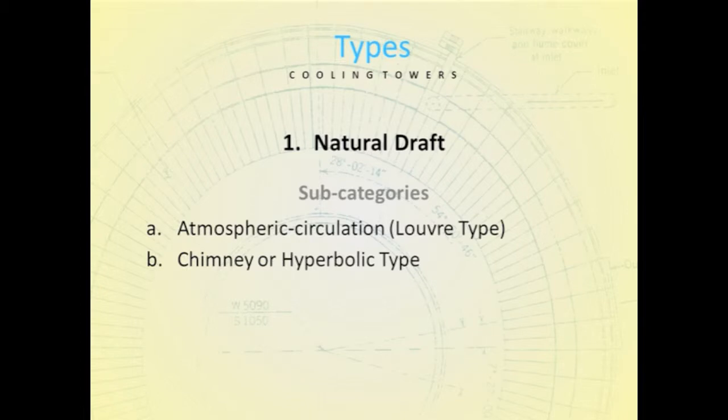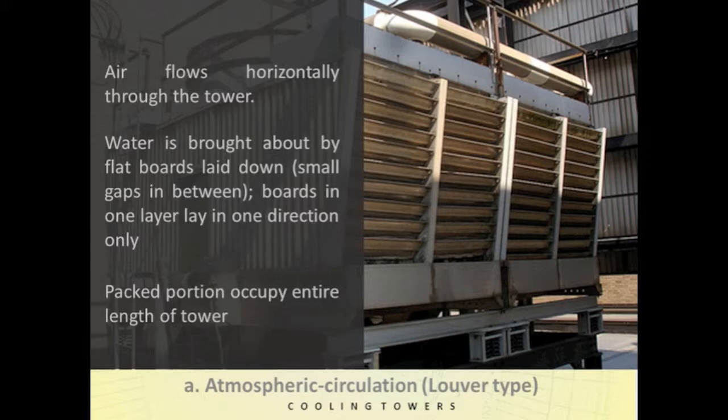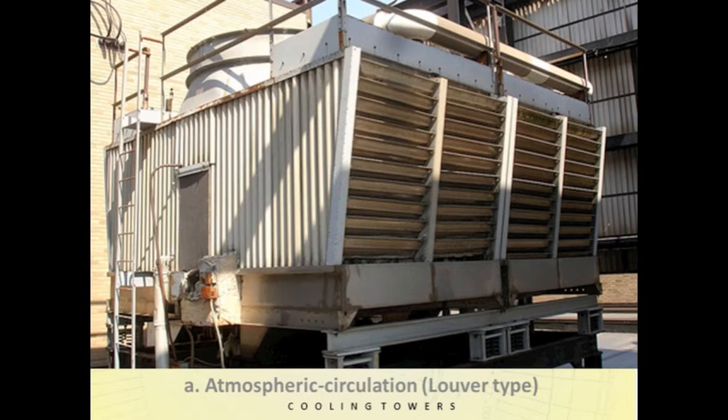We can classify natural draft cooling towers into atmospheric circulation or louver type, or chimney or hyperbolic type. The first type is the atmospheric circulation or louver type cooling tower. In louver type cooling towers, air flows horizontally through the tower. Water is broken up by flat boards laid down. The boards in one layer lay in one direction only, and the packed portion occupies the entire length of the tower. Here is a picture of an atmospheric circulation or louver type cooling tower.